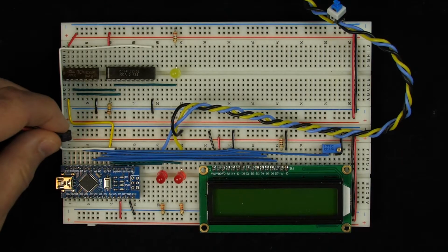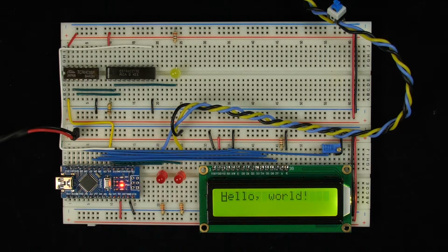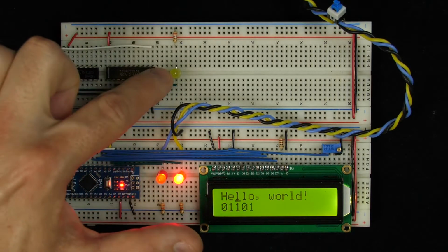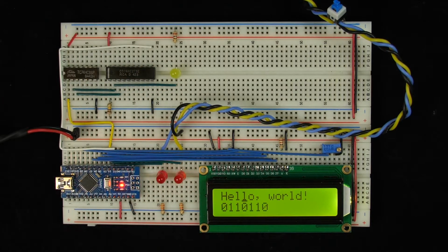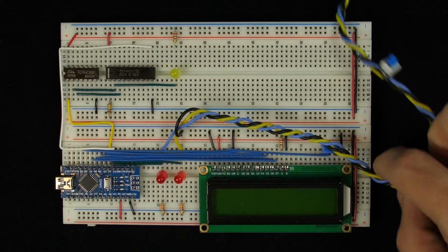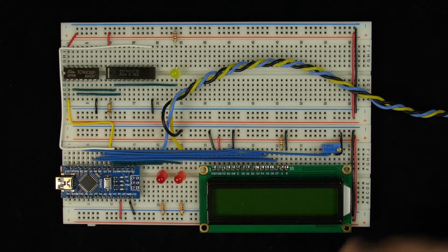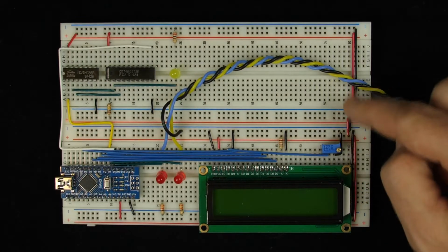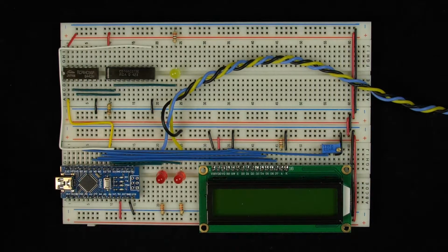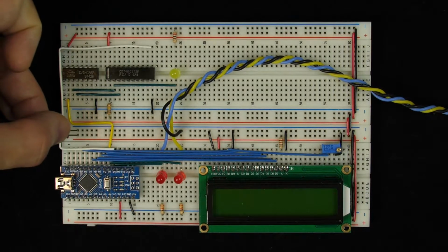So let's power this up and see if it works. And there it goes, and looks like it's not working. I would expect to see this start to alternate. Oh, you know what? I forgot to connect the power. So I didn't connect the power between the two breadboards. So let me just do that. So now we're actually sharing power between both of these breadboards, so let's try this again, power it up and see if it works.